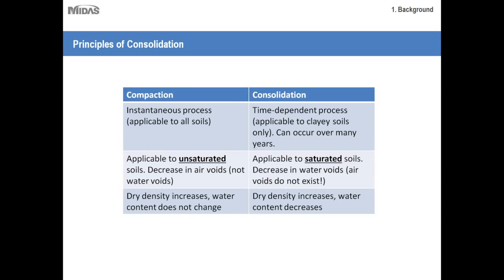Okay, so an important thing to remember is that there's a very distinct difference between compaction and consolidation. So compaction, which I'm sure you're all familiar with, is actually applicable to all soils. It's a very instantaneous process. So just imagine a specimen of sand or a specimen of dirt. If you apply an immediate force on it, naturally there's going to be some instantaneous or immediate settlement. But there's a very big distinction between compaction and consolidation.